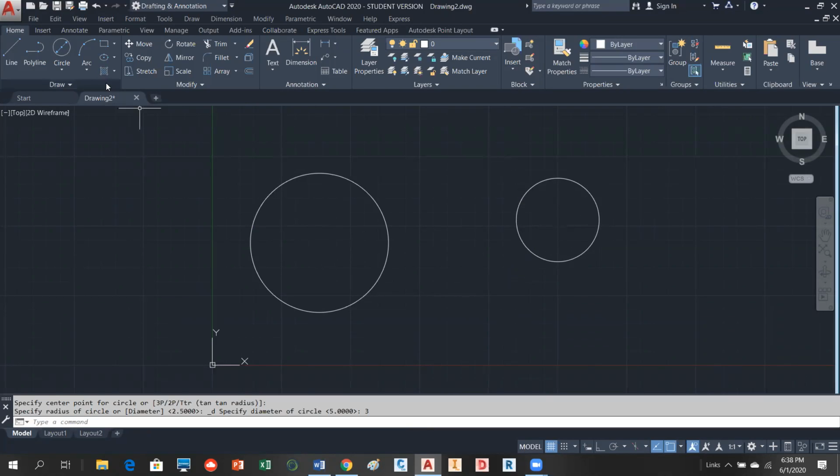Okay, so let's take a look at 2-point. So 2-point you're not gonna use too often, not as often, but again, we're defining points on the diameter of that circle. So if I select 2-point option, you pick the first point, and notice as you drag the circle out, that first point you selected, that's kind of like again, you stuck a pin in there and it's fixed, and it wants to know the circle's diameter.